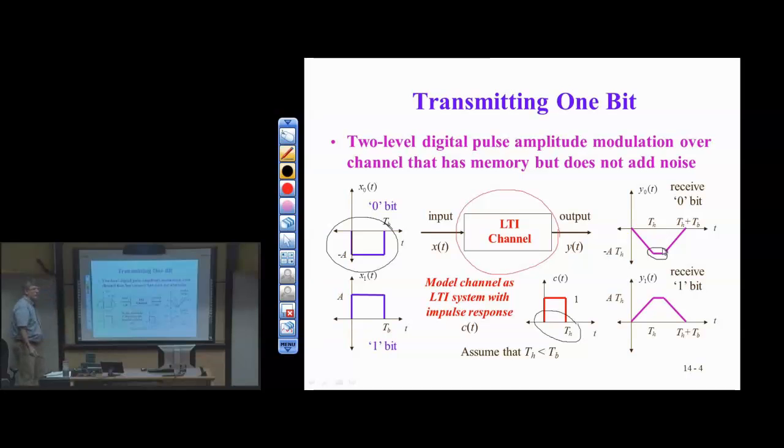I don't have noise, so the sampling works pretty well. But really, with noise, what I want to do is average over the symbol duration. Now, there's a little issue here, as you might imagine: there is a group delay effect. There's an amount of time that the channel needs to fully respond to the input. Now, that group delay, given the symmetry of the impulse response, is what? What's the group delay here?